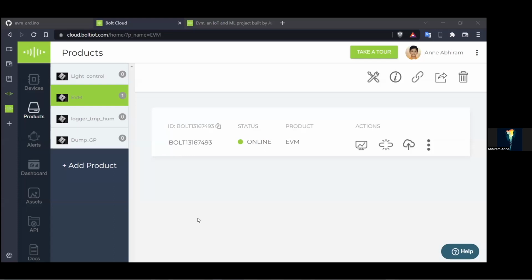I guess a lot of people might assume that if you press the switch, it might be a logic high, but that is wrong. When you press the switch, it is logic 0. So when I press the switch, since it is 0, that is why I have put equal to 0.